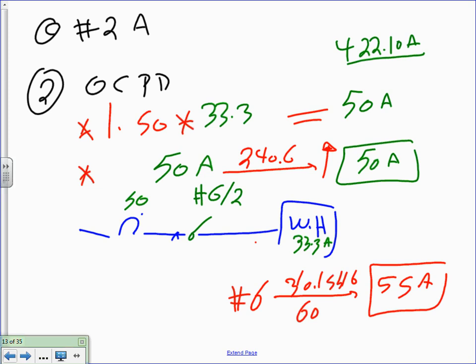The calculation that we do in 422.10(A) is 125% of the marked rating. Why are we using one? I think it's 422 for appliances. I wasn't sure if it was the right reference for it. It's an appliance. 422.10, no, I know, but there's one in 422 for the single non-motor operated appliance.